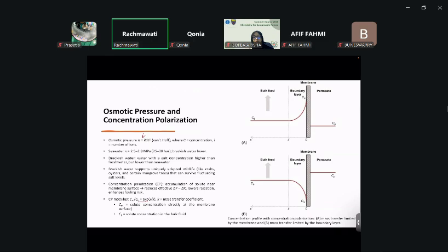So there are actually two types here. This one is the permeate. Let's say this is the clean water that you want, this is the membrane, and this is the feed solution. We have a barrier here, a certain distance above the membrane, in which you have a constant concentration of the feed solution in bulk.